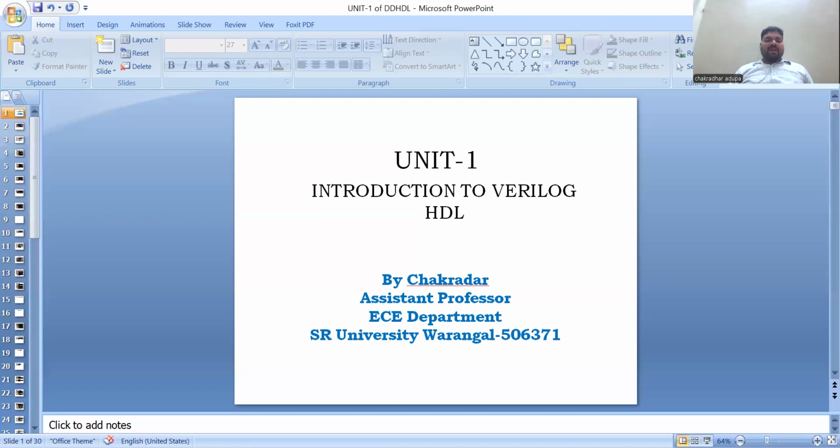Use constructs such as always @(posedge clk), a sensitivity construct in Verilog, for flip-flops, and combinational logic circuits using assign statements or always @(*) blocks. Avoid initial blocks, # delays, or $monitor statements, as they are not synthesizable.